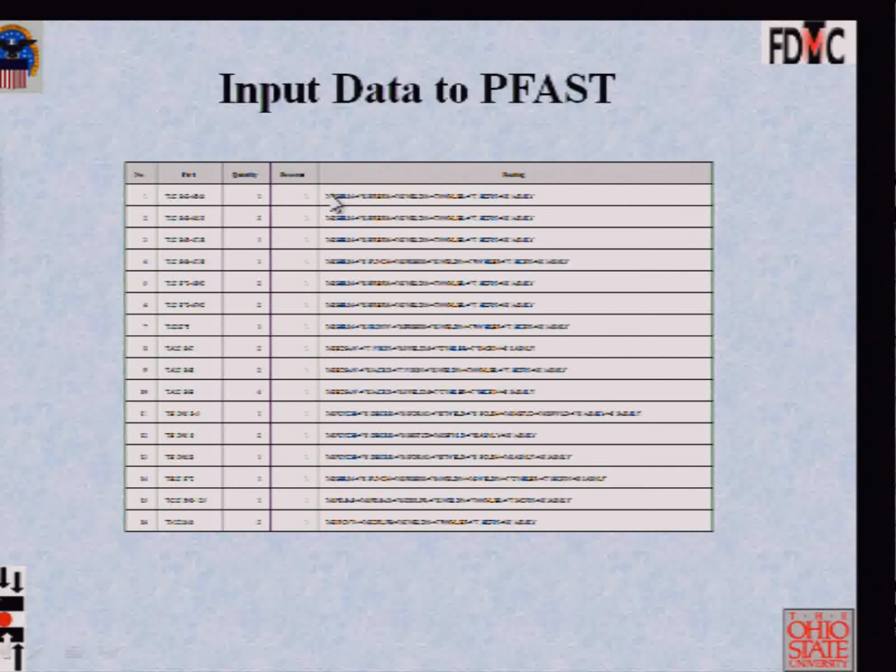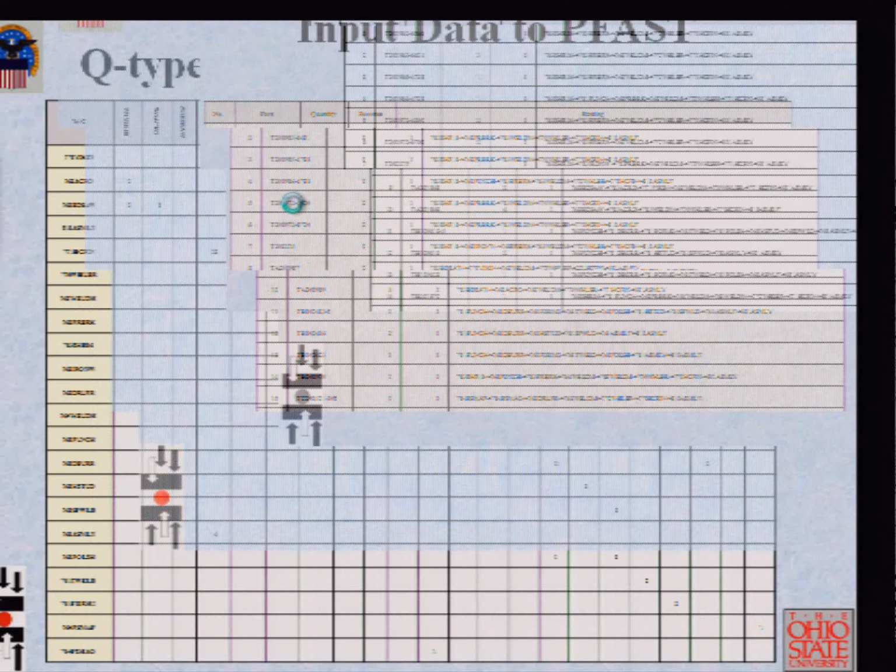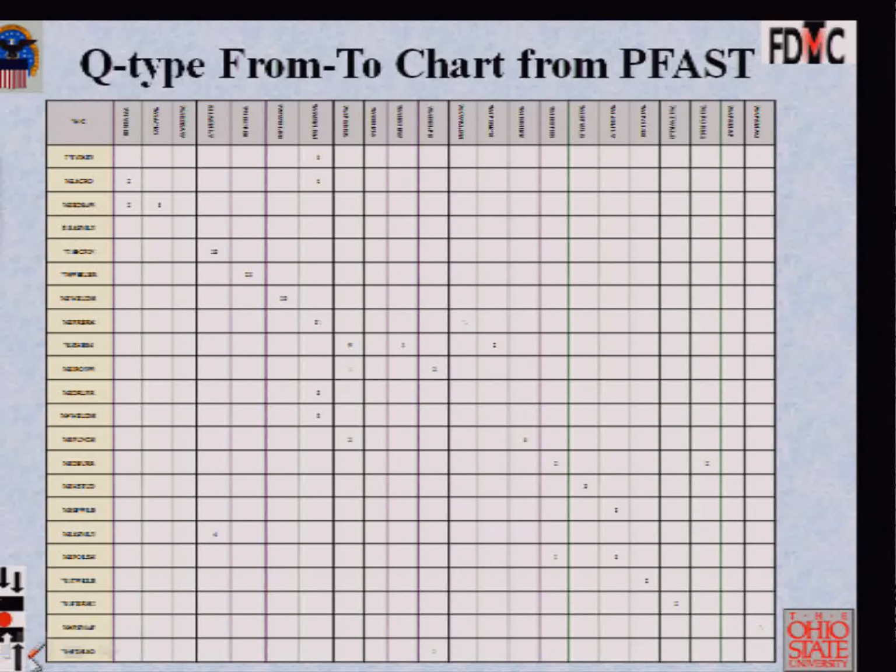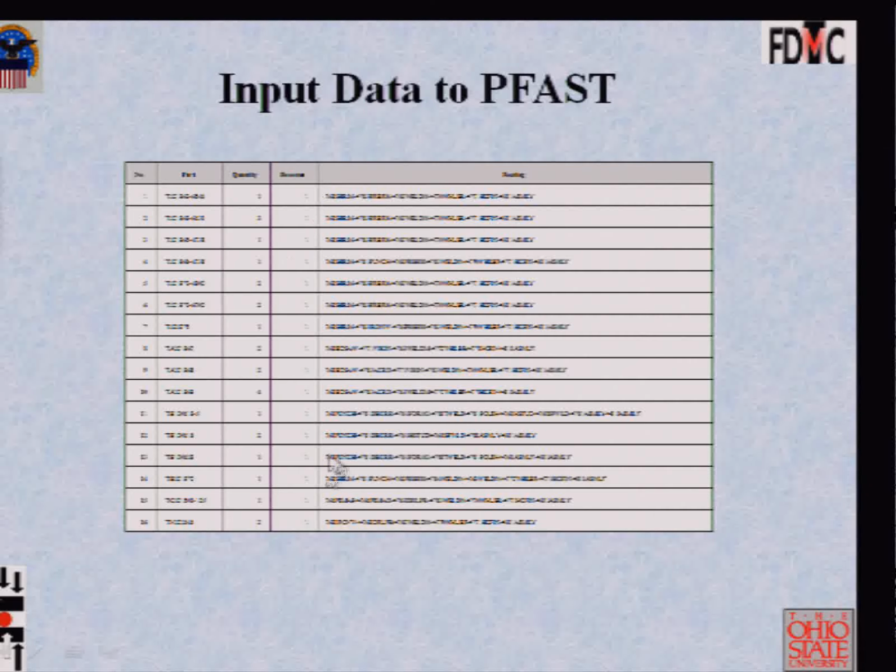Now you'll notice that this routing is identical to this routing, to this one, to this one. Even though these are raw routings, just by eyeballing, you'll quickly notice that there's a family of parts, these 3 parts, and these 3 parts. These are identical, so you would merge those value streams, but then this particular routing, and I think this routing, they're slightly different. So you would not merge them. You would keep them adjacent to the value stream which represents these 3 parts and these 2 parts.